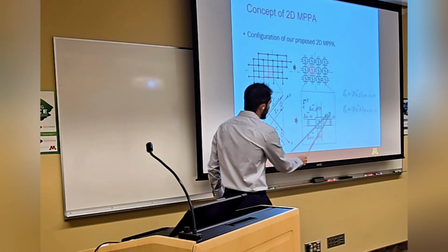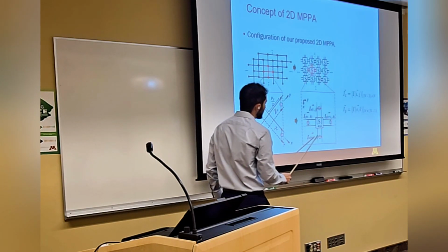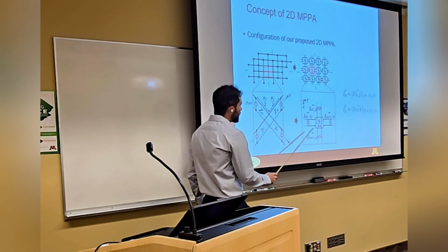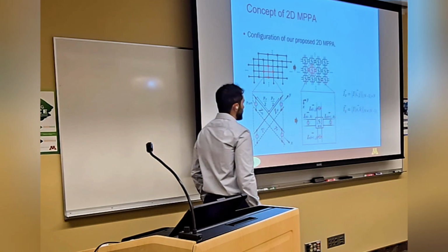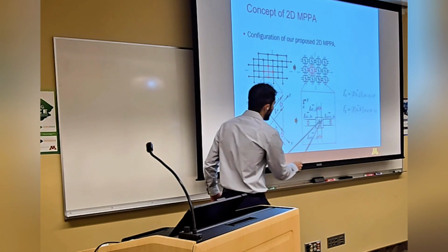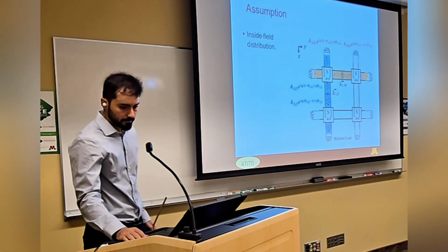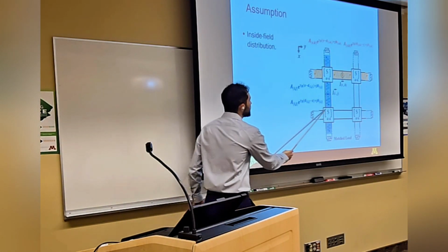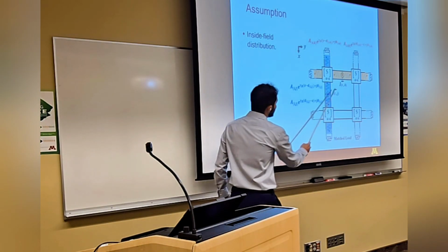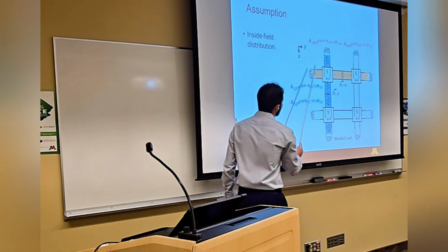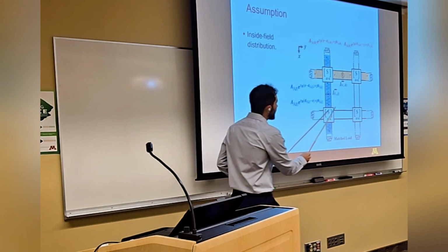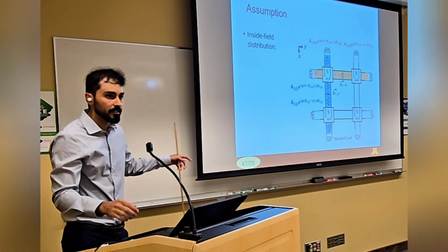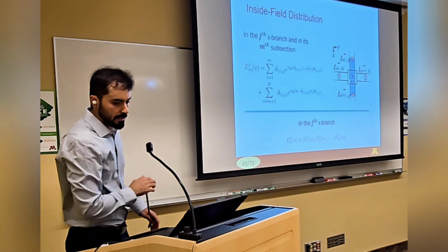Also, we consider 4 ports around the unit cell at the boundaries of the unit cell that inject power into the antenna. So we have 2 different pairs of ports. One pair alongside the x-axis and one pair alongside the y-axis. We assume that each port just generates 2 different traveling waves alongside its branches. And similarly, we have the same for ports located in Y branch. On the other port, we're neglecting any traveling wave in the side branch. Later, I'll show some simulation results that verify this assumption.